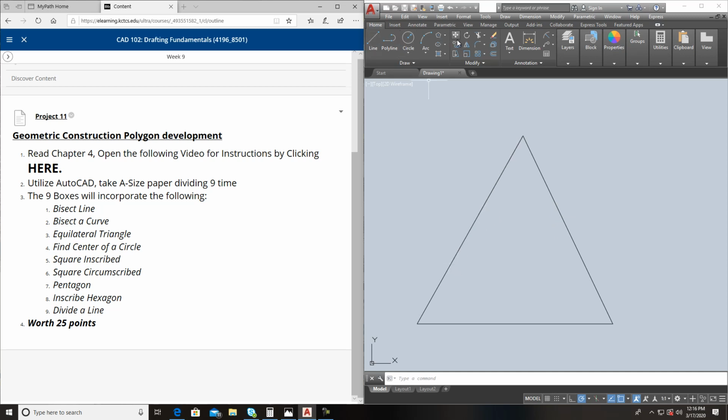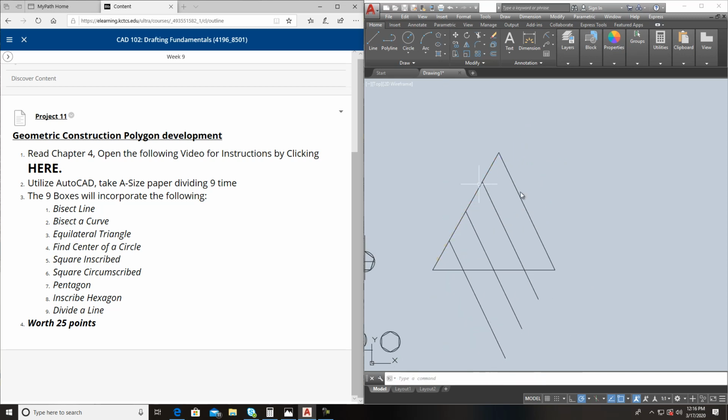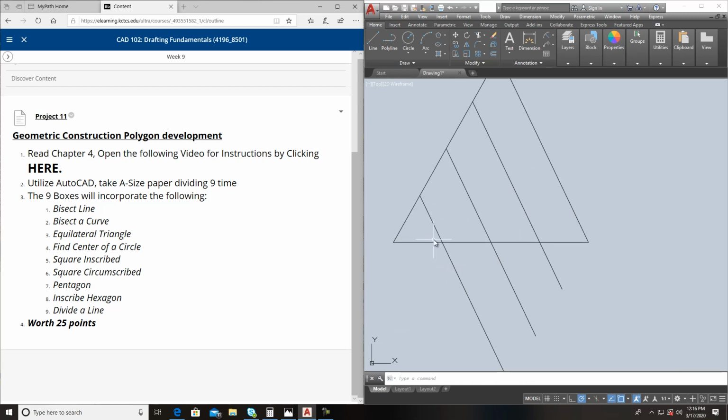So I just do a copy, click on it, click there, click there, click there, and click there. And you'll notice where those cross at is exactly, you busted that line up right here equally 4 times. Does that make sense? So it doesn't matter up here if you got it set 10, 10, 10, or 20, 20, 20, or however, as long as those are equally spaced, and then when you connect these, that these lines here are parallel, it will split this line up perfectly every time.